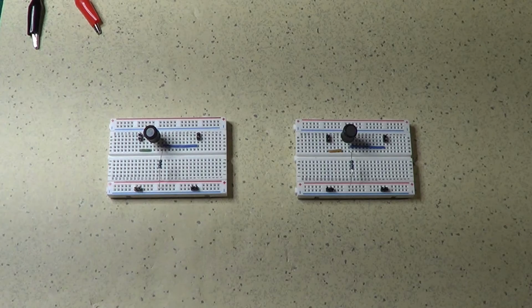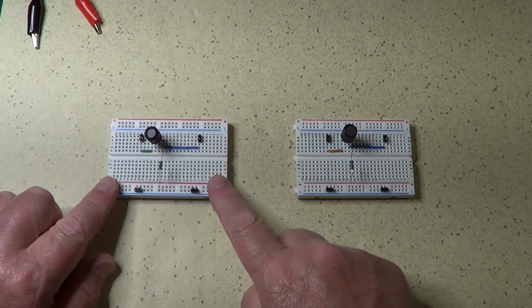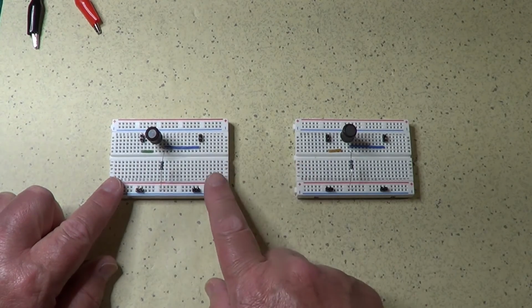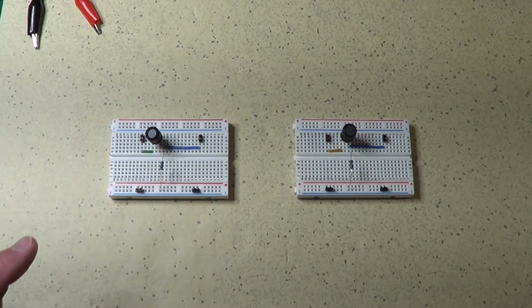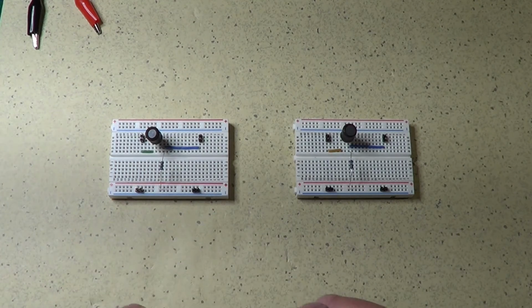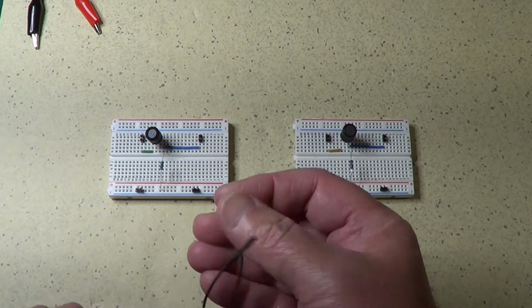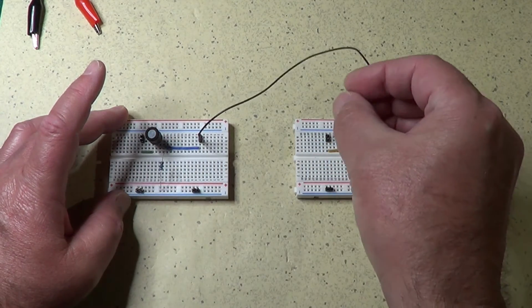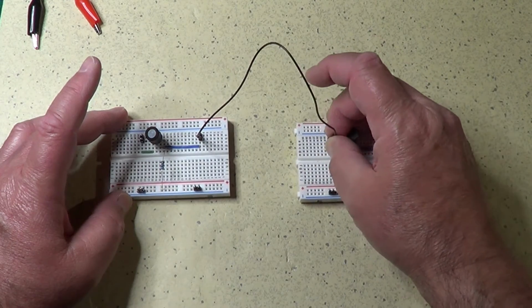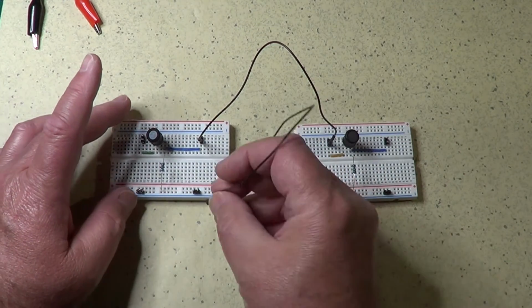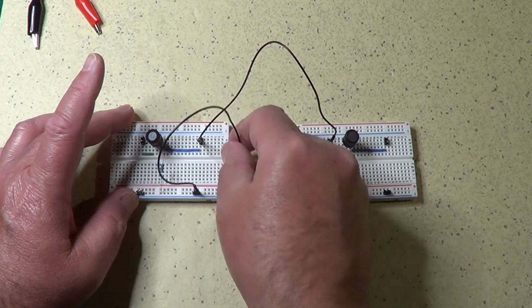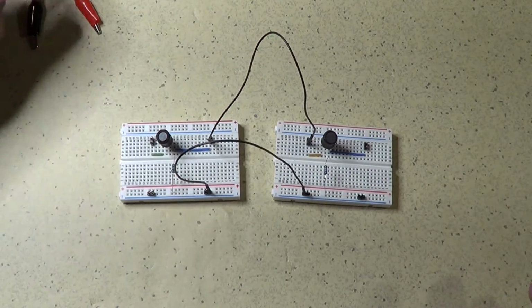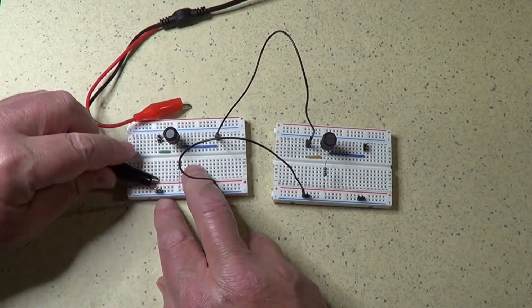To see what happened with the second-order low-pass filter, I built a second circuit exactly identical to the first one. So we have two first-order low-pass filters. And now I will connect the output of the first filter to the input of the next, exactly like we did with the RC filters. So this is the output that goes to the input of the second filter, and this one is ground connection on both of them. So now I'm gonna connect the function generator again to this filter.